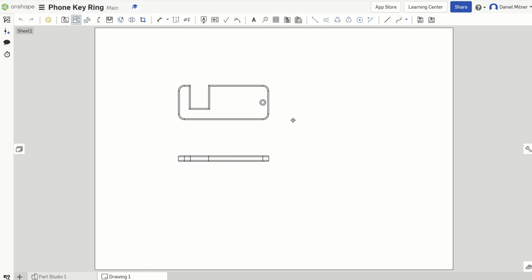So we can draw any other view. How do we draw our end view? Simply left click on our elevation and drag to the right, and we have that generated. I now want to create an isometric. As it stands, I have an orthographic: an elevation, plan, and end view. So very simply, I want to generate a new view. Again, click on my elevation, and I'm simply going to put an angle here, and that will give me that view.